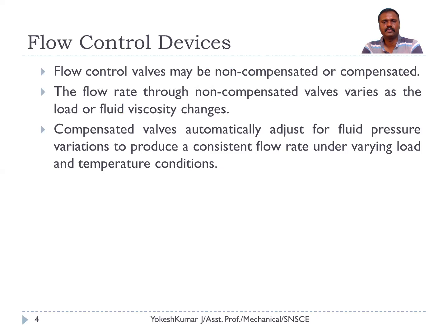The flow rate through the non-pressure compensated valves varies as the load or viscosity changes, which occurs frequently in hydraulic systems. For example, if the cylinder is used to move the bin, every time we cannot ensure that the bin is completely filled or partially filled or unfilled. If the bin is fully filled, then the back pressure created by the fluid is more. So therefore, the pressure difference is very minimal. So the flow rate reduces.